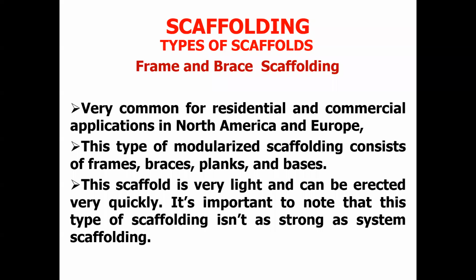For a human being to stay there and do that work at that height, you need to have enough confidence that you are safe. If you're standing on that platform and the scaffolding is shaking forward and backwards, there's no way you can concentrate adequately and do that work. So it's very important that these scaffolds are stiff and firm, and it is the system that gives it that character of stiffness.